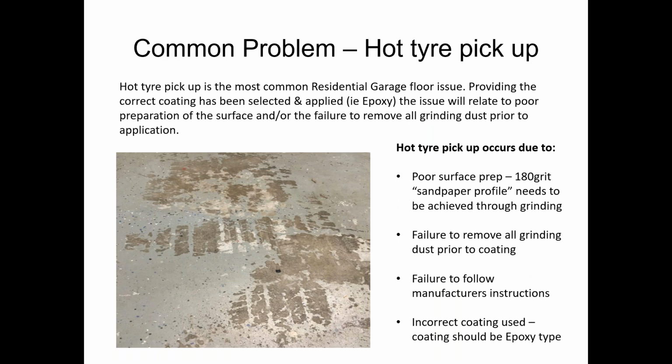And this is your problem that we face often when we have poorly prepared garage floors, low-grade concrete, poor preparation, the wrong paint used, etc. Hot tire pickup is the most common thing, and most of your tires these days, if you actually look at them, have big flat surface areas with ridges in between them, and you come in with hot tires, and sometimes they're wet as well, and it's like a suction pad. If anybody's ever put two pieces of glass together and tried to pull them apart, it's almost impossible. It creates a vacuum. And the same thing here, and it just tears the paint off.